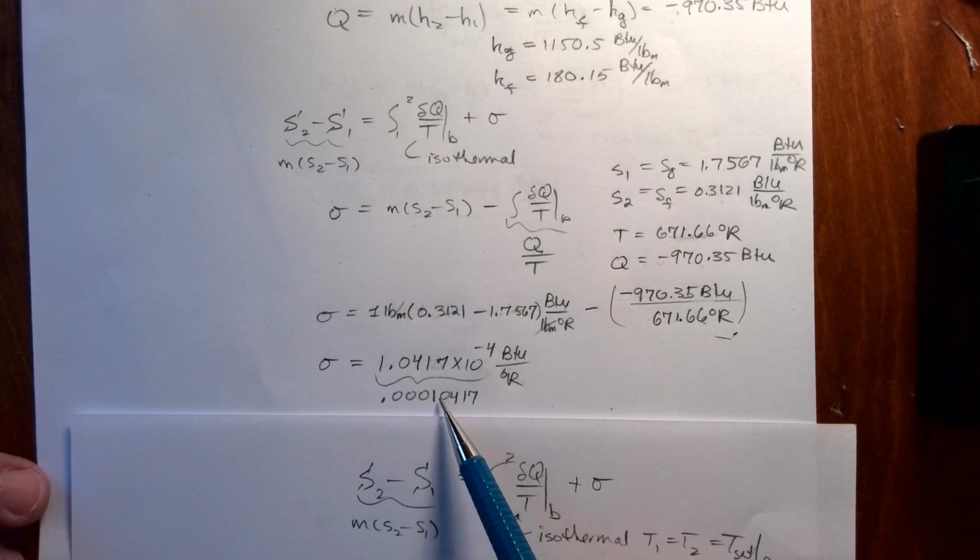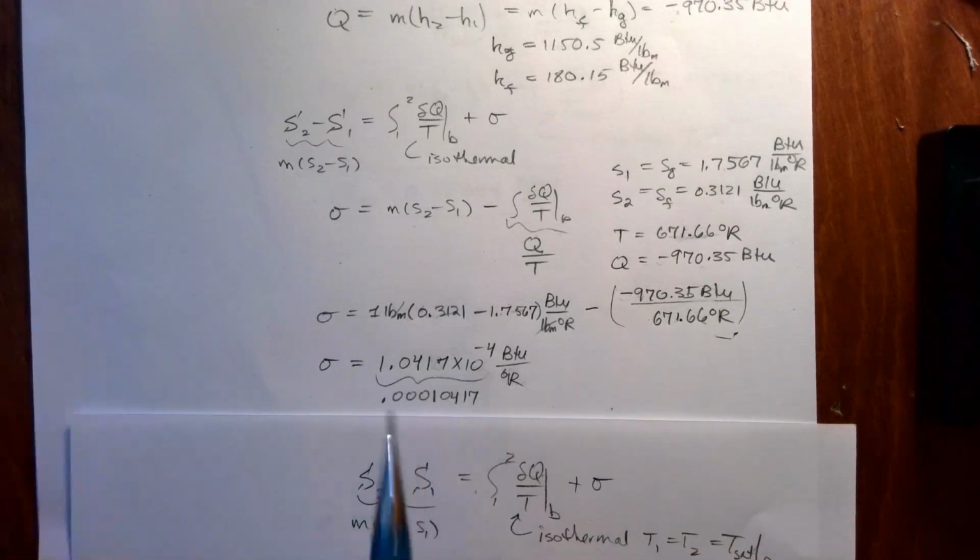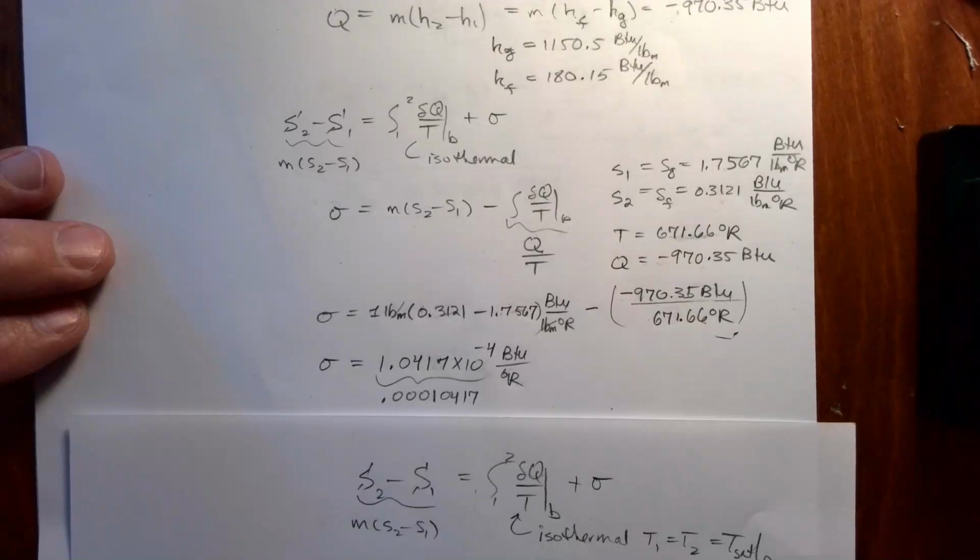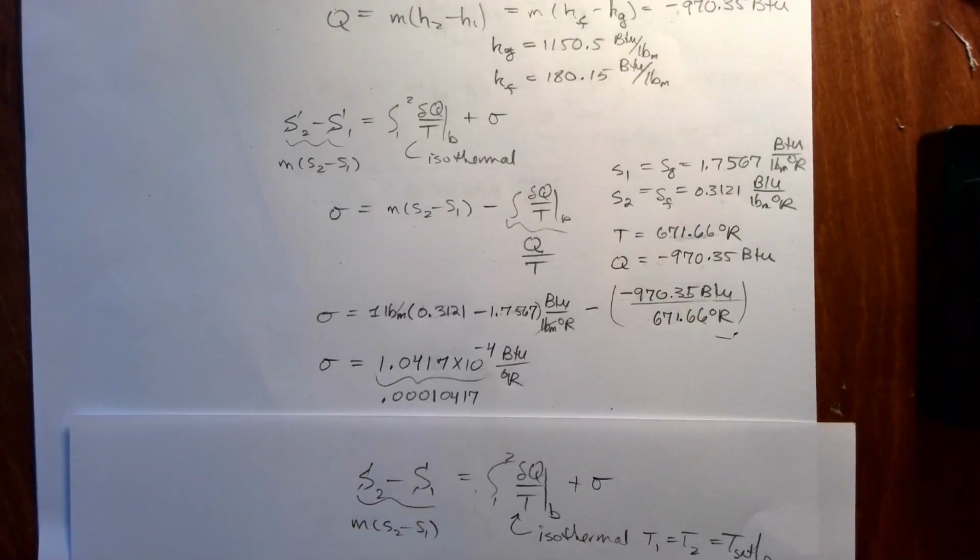So this is very close. You might argue an internally reversible process, but it is satisfying the second law. Very, very close to the boundary. So almost effectively an internally reversible process. I think the textbook solution manual actually calls it internally reversible and calls that 0.